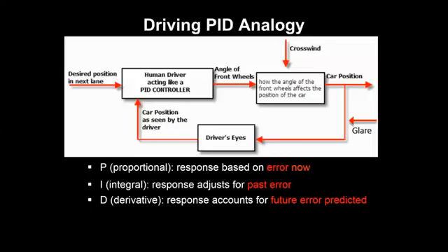We can think of that as a simple example with something like driving a car. If you want to go into the next lane, your brain has become the PID controller. Your eyes are now the sensor input, and your hands on the wheel are essentially the actuator. Now your brain is automatically resetting these types of P, I, and D, because you know that if you make a small change with your hands, your brain may understand that you need to make more of a change, but it's trying to prevent overshoot. And there's different feedbacks associated with that process of changing the wheel, so you can change the position of the car, which is the process variable or what you really care about, and deal with things like crosswind and glare. So you use that feedback to make those moment-to-moment corrections in how much output you have. That's what this PID loop would look like for driving a car.